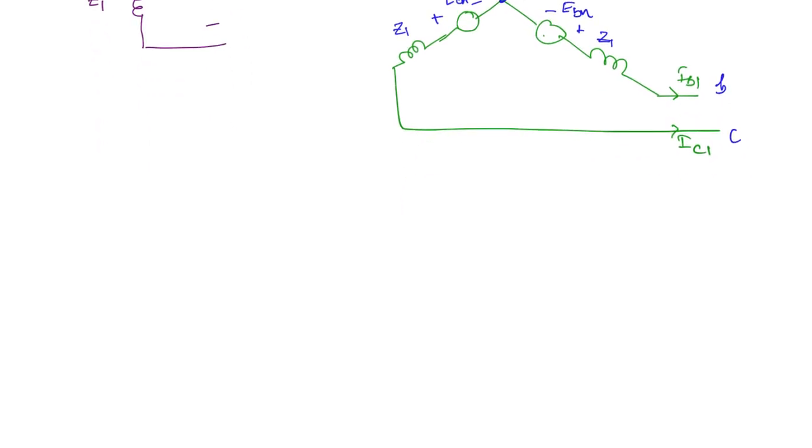Next, the negative sequence network. See here, the negative sequence impedance is not going to be equal to the positive sequence impedance. That point is important. It is just going to consist of an impedance. In positive sequence, we had the internal voltage. Here there is only impedance. The current IA2 will come out like this, and this will be the voltage VA2.